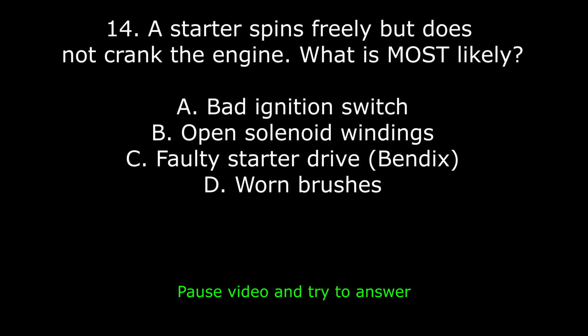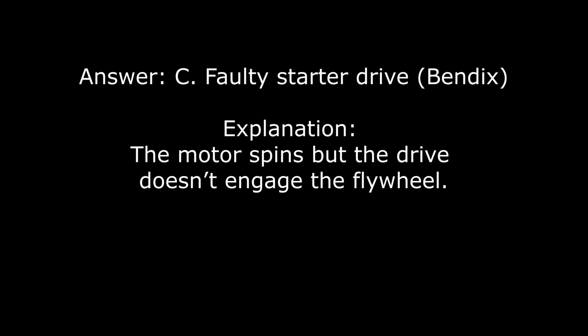14. A starter spins freely but does not crank the engine. What is most likely? A. Bad ignition switch. B. Open solenoid windings. C. Faulty starter drive, Bendix. D. Worn brushes. Answer: C. Faulty starter drive, Bendix. Explanation: the motor spins, but the drive doesn't engage the flywheel.